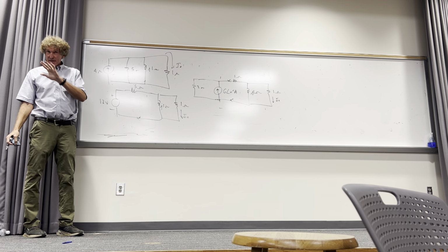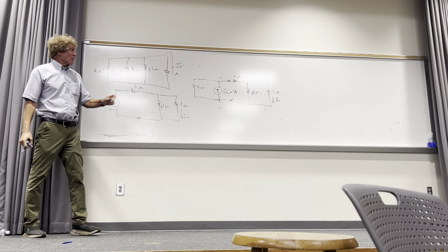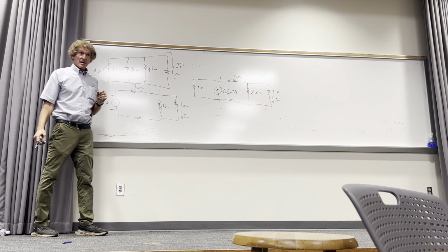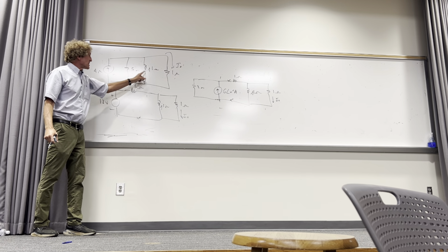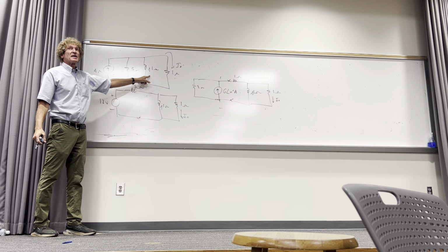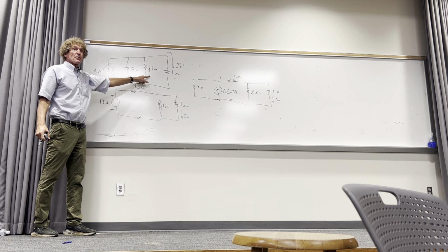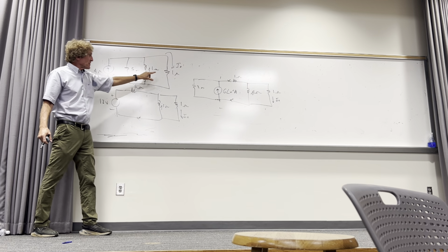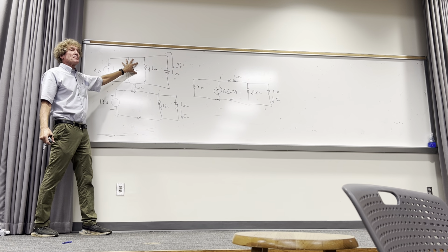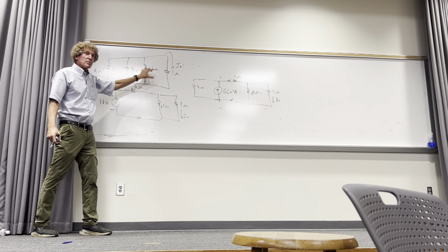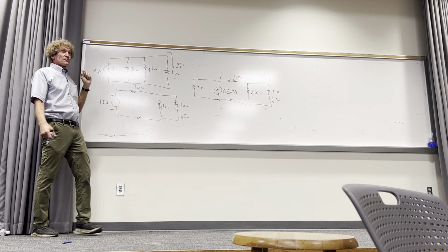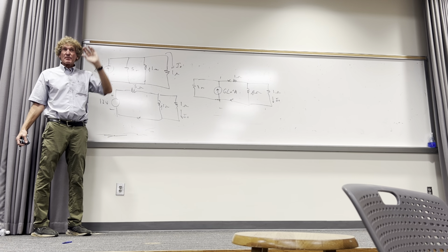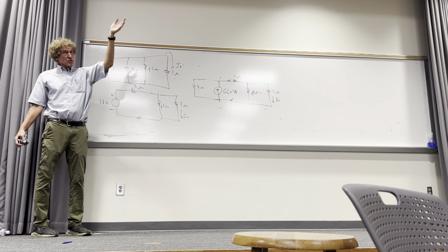Now, hear me. I want this current, right? Couldn't I get a parallel combination of these two as a single value? What is it? Just 3 in parallel with 1, right? J1. And then you would have a net impedance here. And if I wanted the net current there, it would be that net impedance over the sum of 1 plus that impedance times 4, right? How many see that? Sure, you could do that.